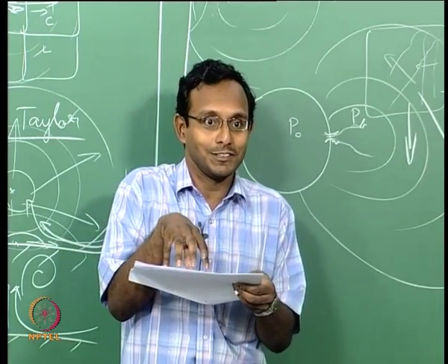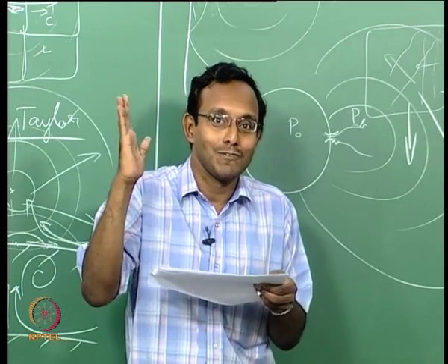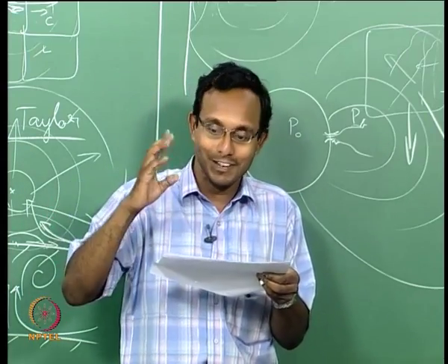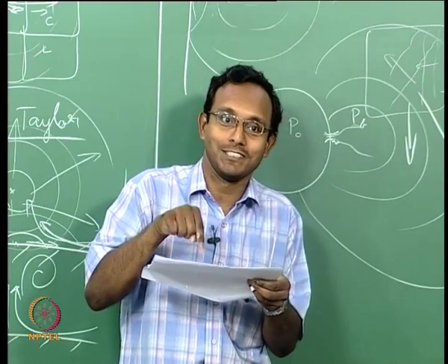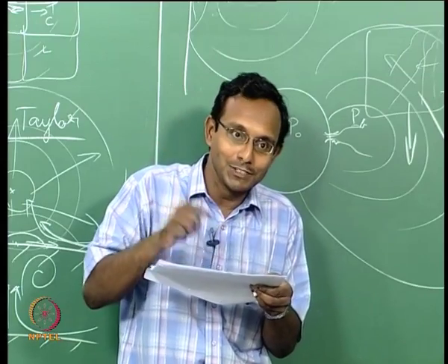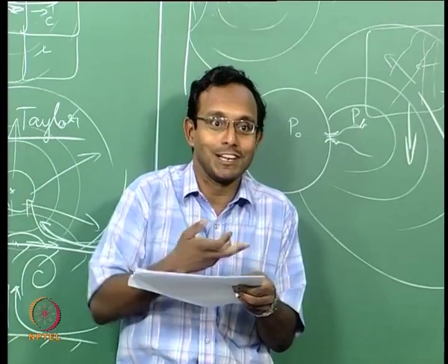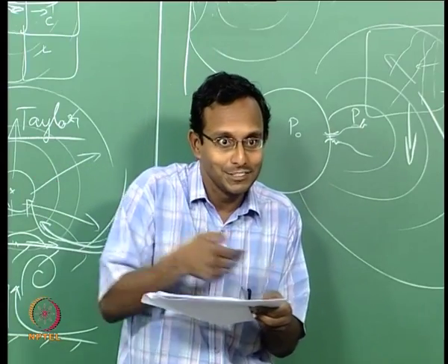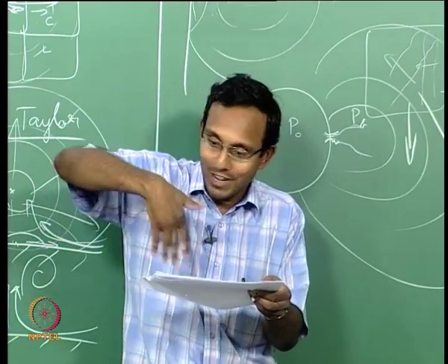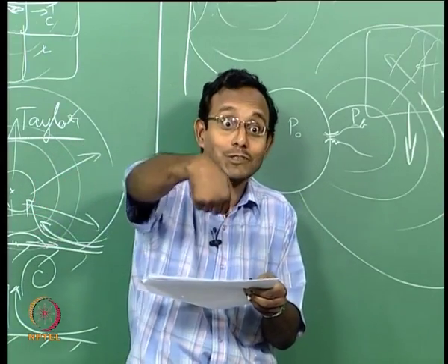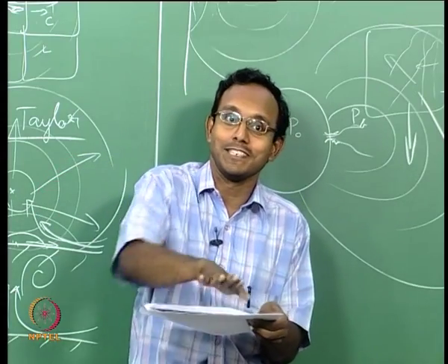Inside it is high pressure, and how did it become high pressure? Wall moved in, compression waves bouncing up and down inside here, that increased the pressure inside. While it is bouncing up and down this way, it is also going out on the sides. Remember, it is a spherical wave, goes in all directions. When it goes on the sides, they see nothing. What will it do? It will keep traveling, because of that it will induce a flow along with it. So flow starts escaping in all sides.